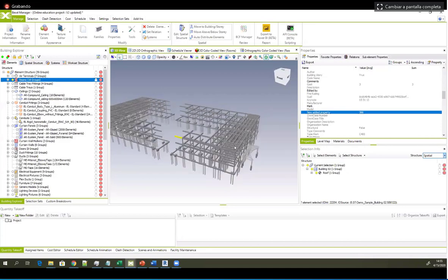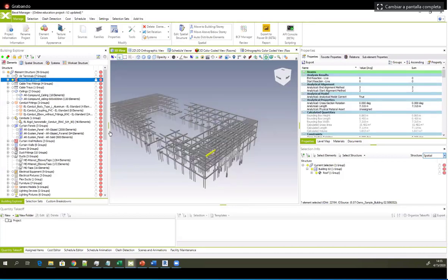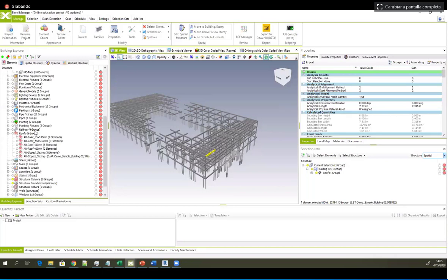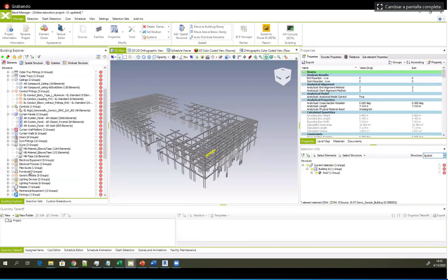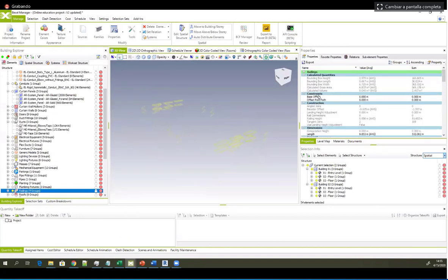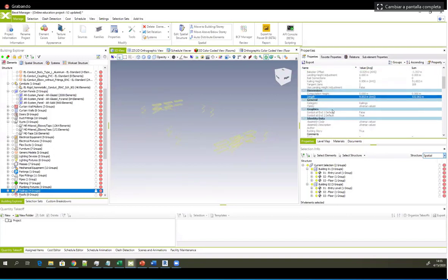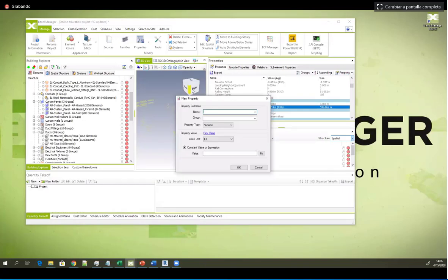Of course, this is not just that. So you can also use the formulas to add some additional property which are not available. So for example, if in this BIM model I select my railings, let me just find the railings, and I can isolate only the railings from the BIM model. You see that the railings, for example, have the length and have the, let's say, computation height, but these elements do not have the property area. And if we want to get the area from these elements, we can do it again using the property new option and add new property to these selected elements.